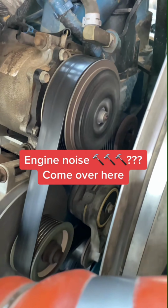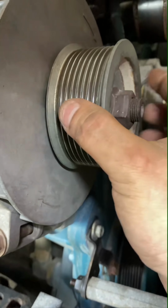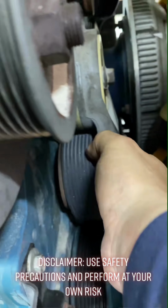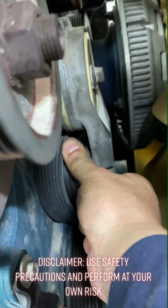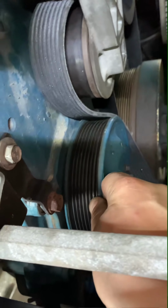If your engine's making noise like this one, and your belt is worn like that one, come over here. Obviously replace the belt, but also check your pulleys. The alternator's okay. What about the tensioner? That one's all right. What about the water pump? Notice how this one has excessive play. This indicates that your water pump is worn, so it's gonna need to get replaced.